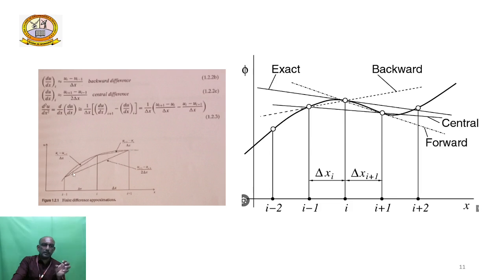So this line represents the central difference. Central difference considers the forward direction point as well as the negative direction point. So this is the central difference method: u of i plus 1 minus u of i minus 1, divided by 2 del x. We already discussed this in the previous slide. So from the approximation, we approximately predict the flow properties in the curvilinear path. For that only, we use this approximation approach: forward difference, backward difference and central approach.